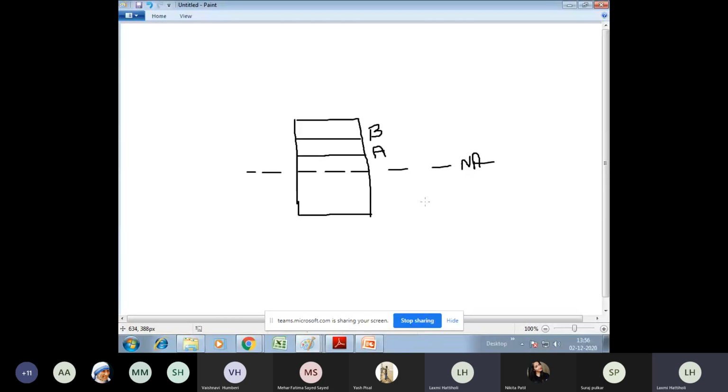Yes, your answer is very correct. It is maximum at the B point. Why? From the neutral axis, Y is maximum towards B, ma'am. Okay, may I know your name? Shilpa, ma'am. Okay, Shilpa, very correct. As Shilpa said rightly, when the distance from the neutral axis increases, obviously your bending stress goes on increasing and it will be maximum at the top, right?